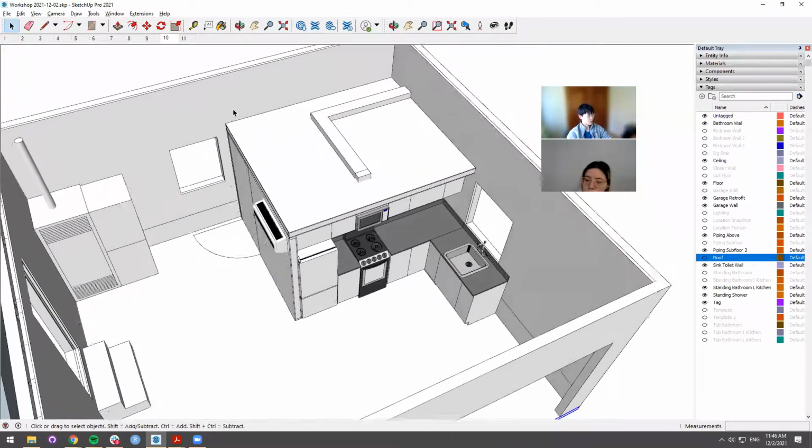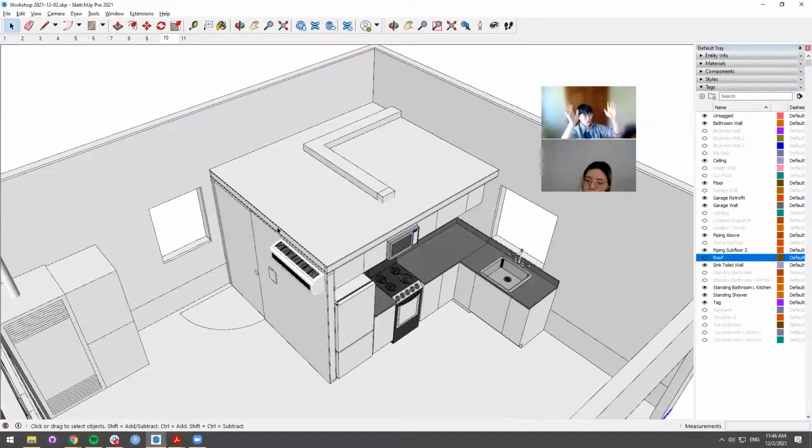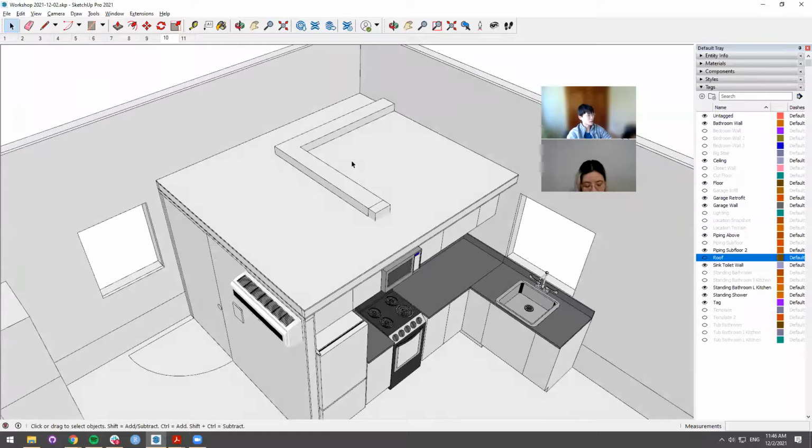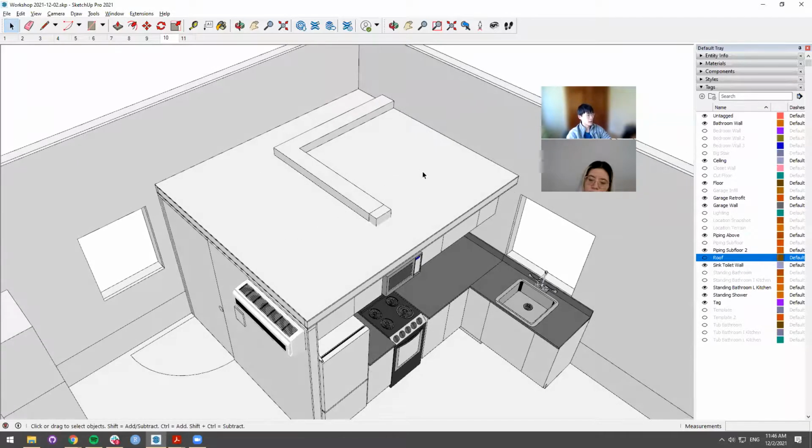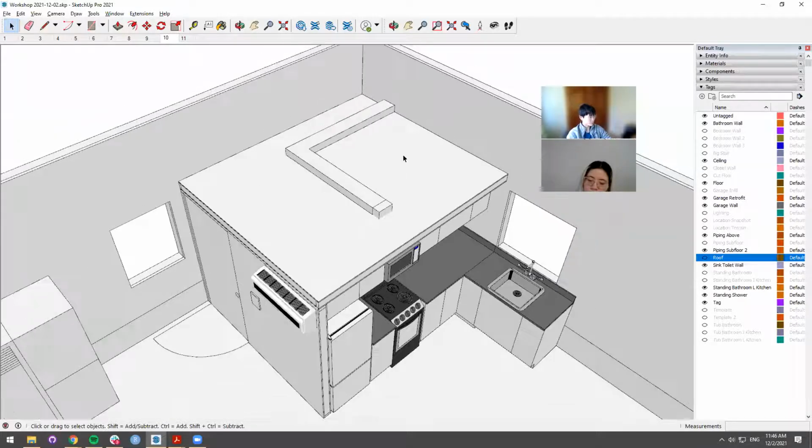And then we add a ceiling, or you would do kind of filler wall, but the ceiling is going to be necessary at some scale for dealing with the lighting wiring, as well as the exhaust duct for the range hood, and for a bathroom exhaust fan. So this is showing a potential rectangular duct that's just on the top of the ceiling where nobody would see it, going to an exhaust vent sideways, which we would assume is easier than going up through the roof. And other kinds of metal conduit for electrical wiring can just run at the top of this as well.